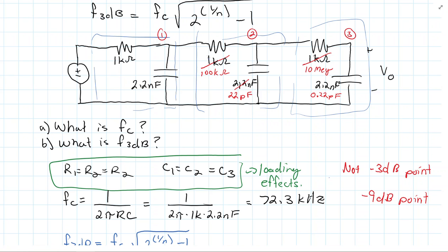Now, as a simulator, we can always simulate it, and the simulator is just a number cruncher, so it's going to say, yep, it works. But if you were to try to build that circuit on a breadboard, you probably would not get the results that the simulation was giving us, because there's all sorts of stray capacitances in those breadboards. All right, but it is something interesting.